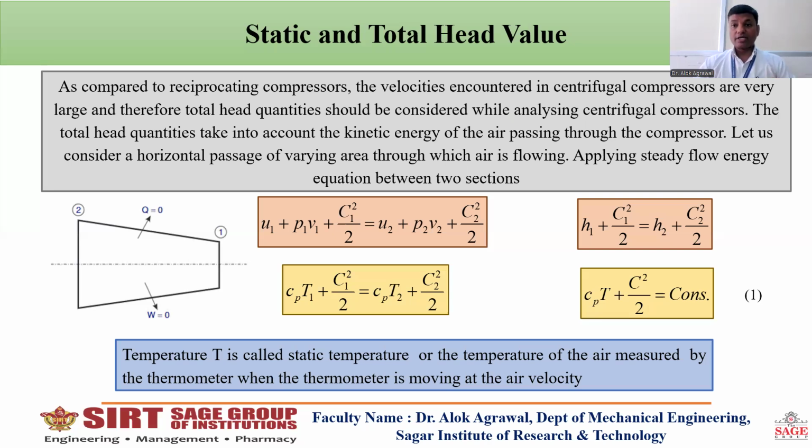Now, what are stagnation temperature or stagnation properties? Here the measuring instrument is stationary and the flowing fluid flows around the measuring instrument and goes on. The fluid which comes in contact with the measuring instrument has its kinetic energy reduced, because when it strikes the instrument, its kinetic energy becomes zero. The complete kinetic energy is converted into another form of energy, say temperature. Whatever reading the measuring instrument gives is not the static temperature, it is the stagnation temperature.